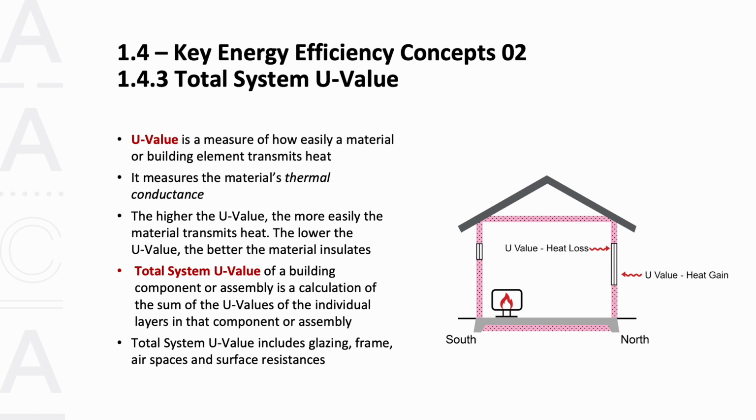And you'll usually see U values quoted for glazing and window systems. You need to understand whether the value quoted is the value of the glass or frame or a total U value for the entire window system.